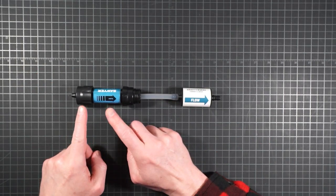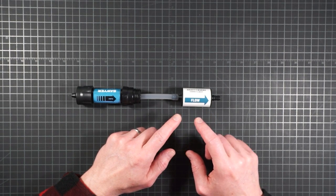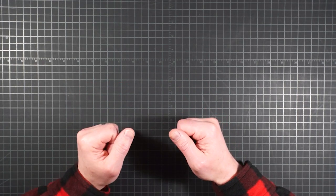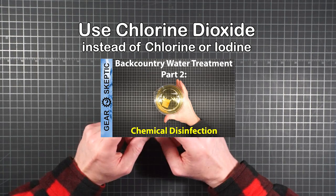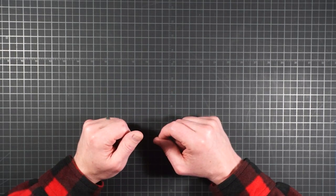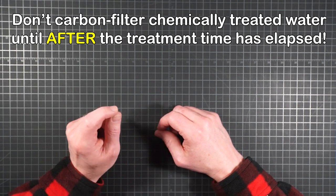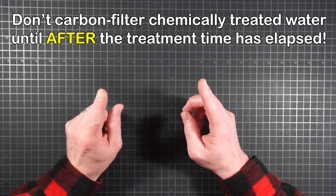And once you've strained out the germs and the silt, the granulated activated carbon is there to pull out most of the swamp taste or bad odor that might remain. Another way to use a carbon element like this is in combination with chemical treatments such as iodine or chlorine. So my first suggestion is to switch to a chlorine dioxide based chemical. See part 2 for details on why. But failing that, an adsorption post filter can help reduce the unpleasant chemical aftertaste. Just make sure you don't carbon filter the treated water until after an ample amount of time has passed. Otherwise, you'll just be removing the active chemical ingredient before it can disinfect your drink.